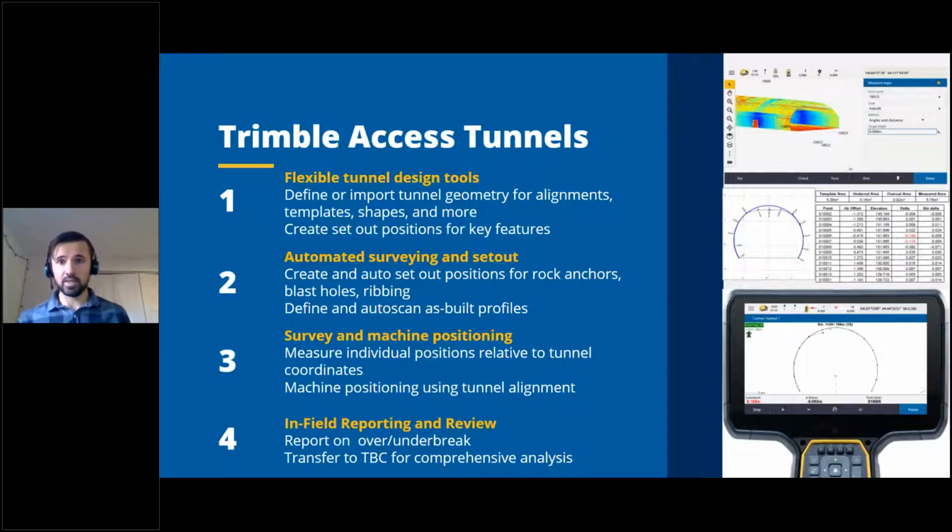Now from there, once you have all that design, you do the automated surveying setout. If you're doing setout points, if I'm setting out blast holes, I can automate it. Say if I need to mark those points, I can set a time interval where it will stake out and automatically move to the next point, giving me enough time to spray paint or mark the tunnel surface. As well as automated as-builting profiles, which I talked a lot about already, and I think that's a key feature, especially for productivity in tunnels.